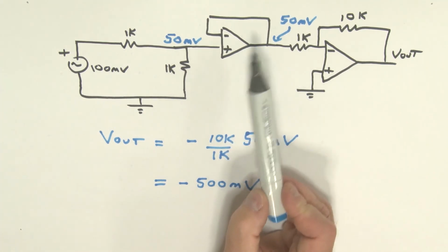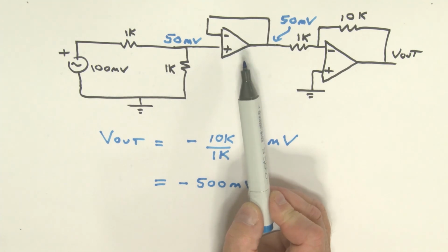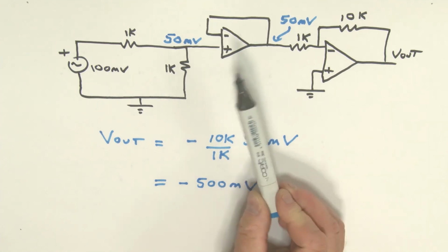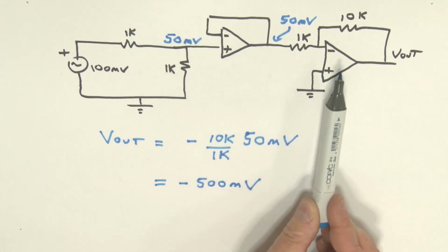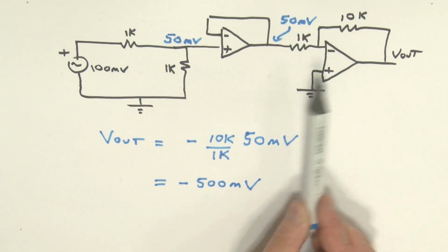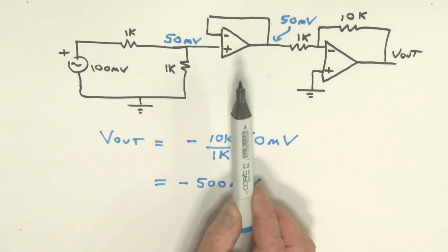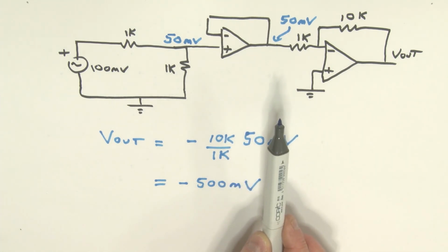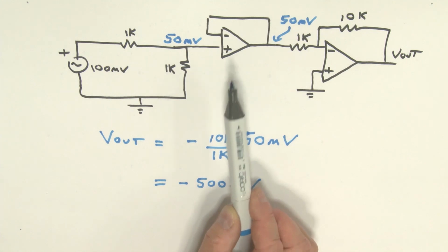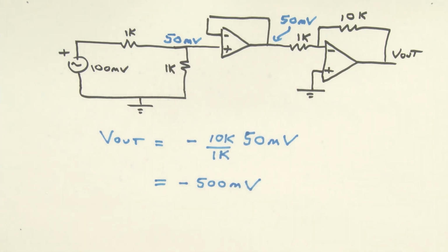So this voltage follower basically has acted as really a buffer between my inverting amplifier in this case and this little potential divider circuit over here. And that's one big application really for voltage followers, is that they're used as buffers.